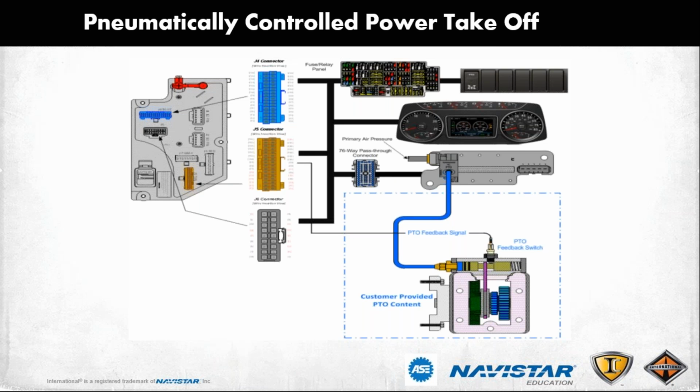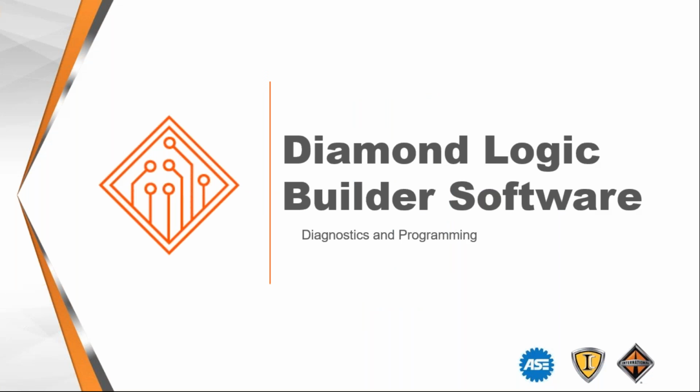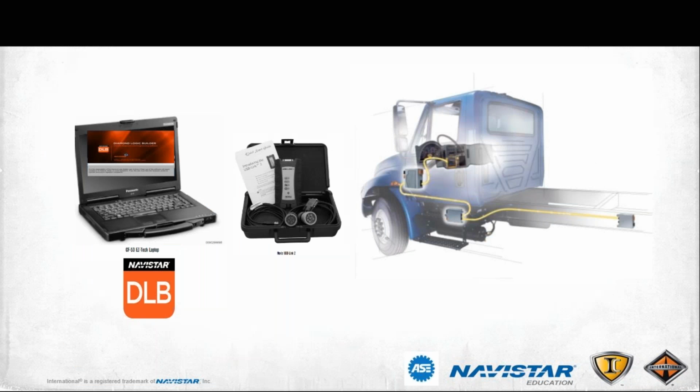Once we connect to the vehicle and open up the software, it looks something like this, okay? What I have highlighted here is a VIN. We're just going to hit a couple of the tabs. There's a faults tab. So if we were here to check the faults on the vehicle, once we're connected and we make sure our key is on, okay? These will connect at key off, but after it's fully connected, you turn the key on. We can take it out of editing mode. If you look in the upper right-hand corner, it says the word editing.